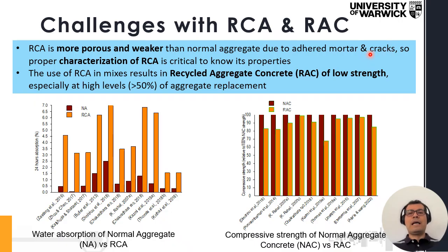The other issue we have with RCA is the way we recycle RCA. Many of the times, what we do is mechanical recycling. So basically, we crush the old concrete to produce the chips and the new gravel for the RCA, and that creates cracks and it creates also damage in the gravel and in the little pieces of new aggregate. And as a result, we need to understand and characterize RCA properly to know its properties and to know how to utilize it properly to produce a new RAC.